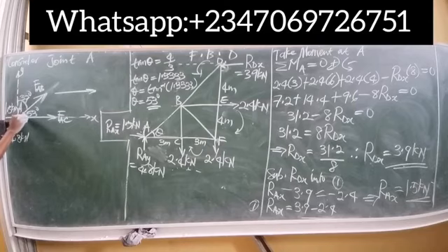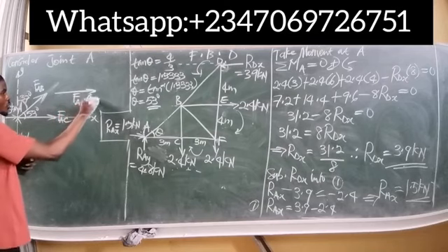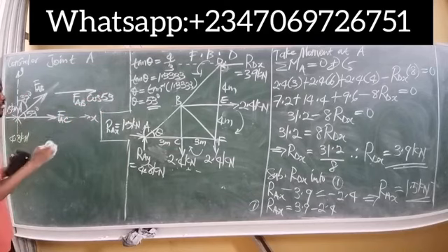So if it passes through this angle 53, all you need to do is simply multiply this force by cosine of the angle it passes through. That gives you the value of the horizontal component of this force. So I will simply have that force to be FAB cos 53, cosine of the angle it passes through. So this is the horizontal component of this force.